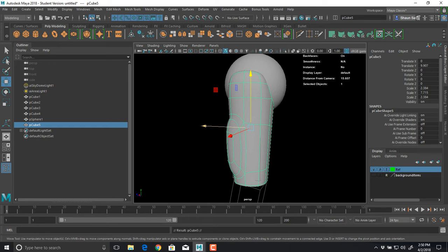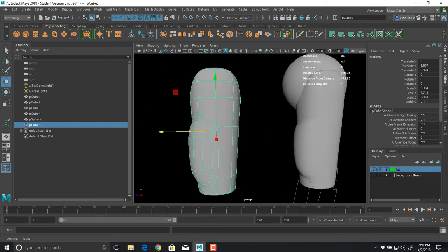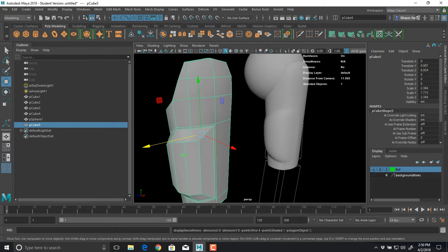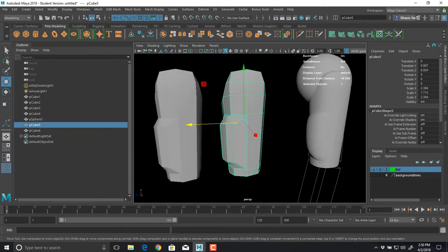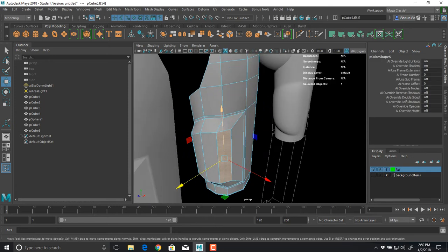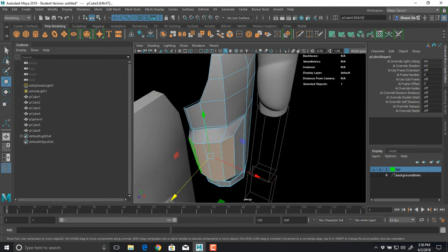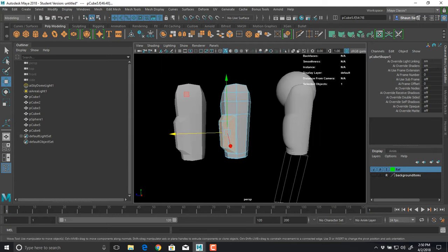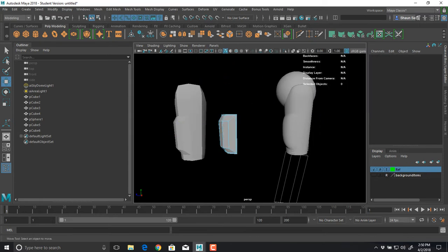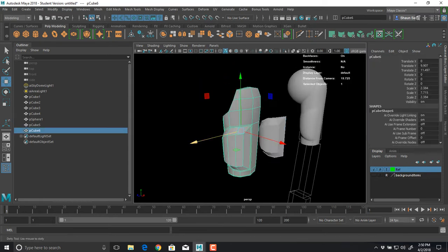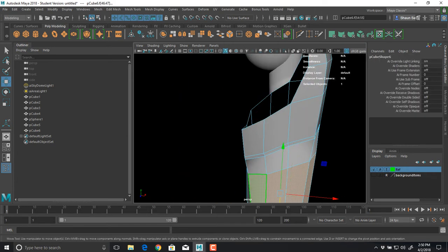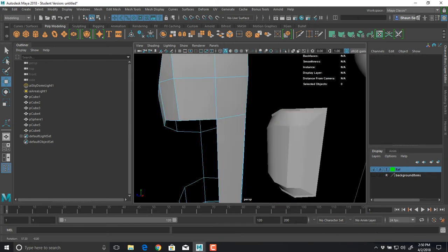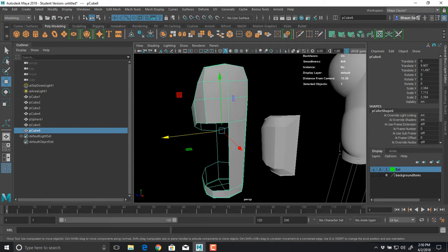So I'm going to duplicate this just so I can show you the purpose of doing this kind of thing. I can use this shape as 2 surfaces. So if I take one of these and I keep this, and I'm going to use Shift greater than to grab that, and then I'm going to hold Shift and marquee it and delete the rest of it. And then I'll do the same thing on here, but I'll delete the opposite pieces. And then I can put these together.